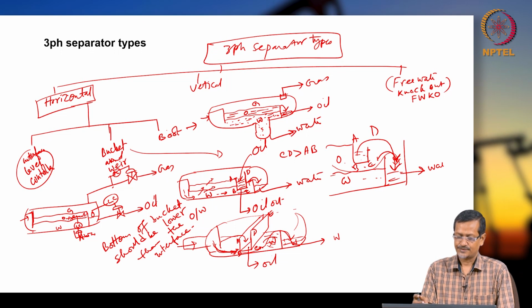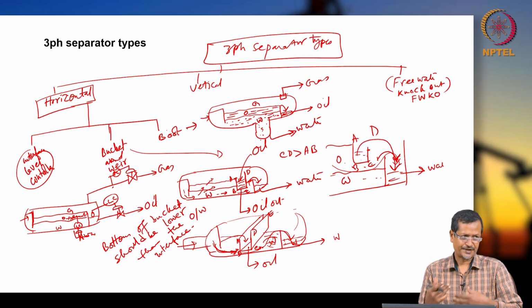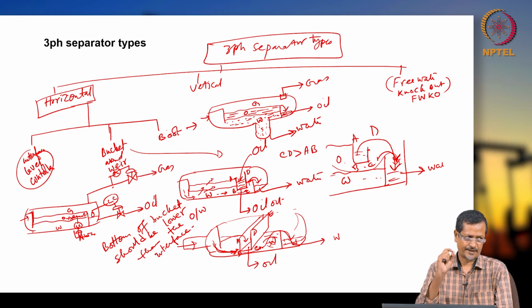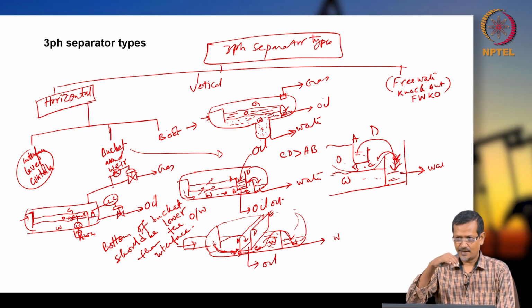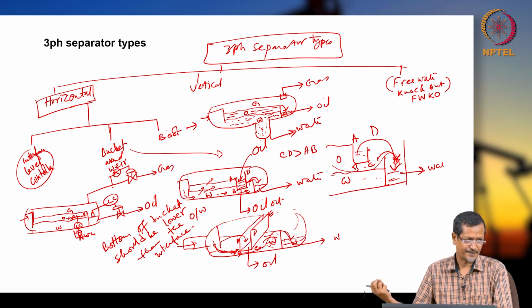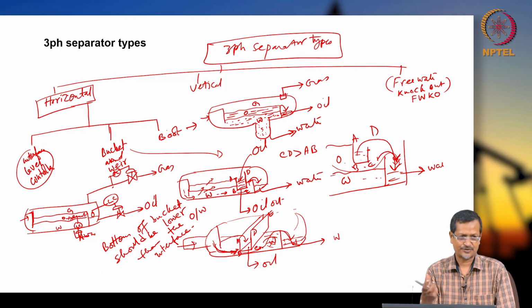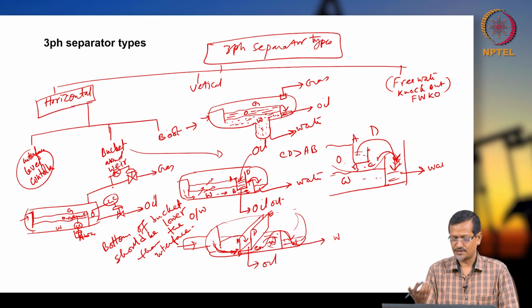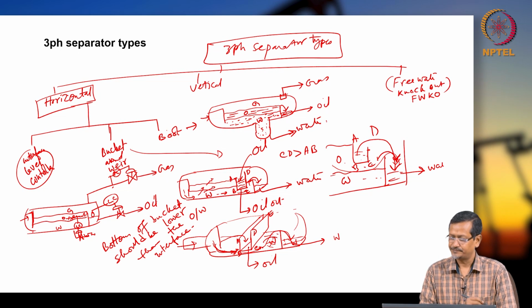You can see this in the boot case. You see one small portion, a large portion is there in the separator. What happens? This will create a very calm environment, so that oil particles will be moving up slowly, and water will be collected there. From there, a small amount of water you can collect and separate. So it will not take larger space on your separator system. Rather, you are getting a small chamber where you are getting your things separated. Fine.